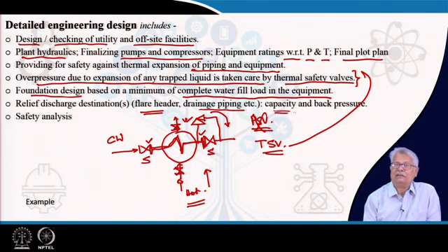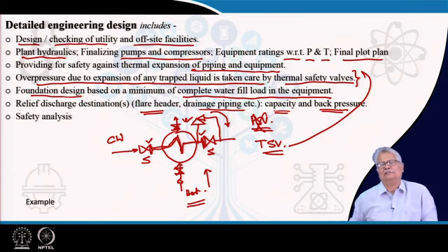It is very important to note the capacity of the discharge system which receives the supply during the discharge itself. Another thing, the discharge is against a back pressure. So, if your back pressure goes up, the safety overpressure under which the safety valve operates will also go up, and this may be a threat to your equipment. So, you have to ensure such a design of your relief discharge destination which will have a fairly constant back pressure, and if it is not, you have to use special type of relief discharge valves.